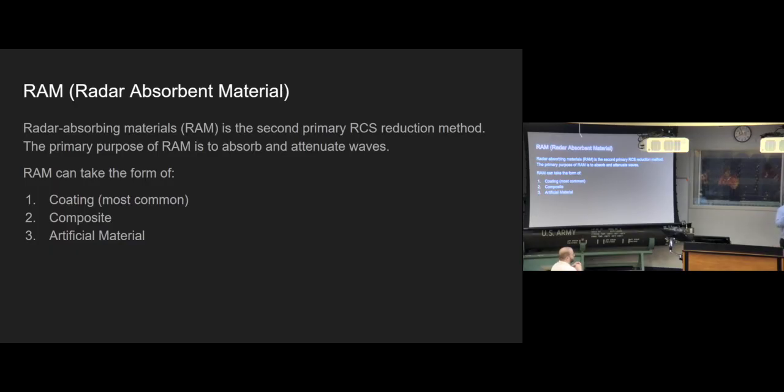Composites, nowadays we're starting to get into the advanced realm of where we can start replacing that pesky metal that reflects radar real good with composites that might be transmittable to it. It'll send it right through. Now, that's not actually as great as it sounds. There's a concept called radar penetrability, which is if your vehicle was this super lightweight carbon fiber composite, it still has metal engines, it still has metal circuits. You're gonna send that radiation up through there, it's gonna go right through your composite, good job, it's invisible, and then hit your engine and reflect like, again, Christmas light. So they have their uses, but they have weaknesses.